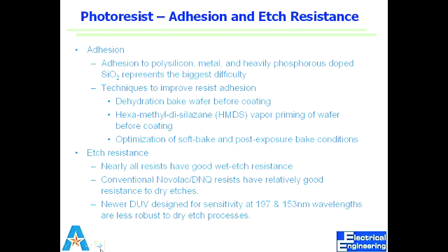We use a chemical called HMDS. Last time we saw that process of applying photoresist where you dispense it, right? That video was probably of the advanced automated systems. But generally what we do is we have the wafer static, we don't rotate it. We put a puddle of resist, we cover the whole thing with resist, and then we start the spinning.